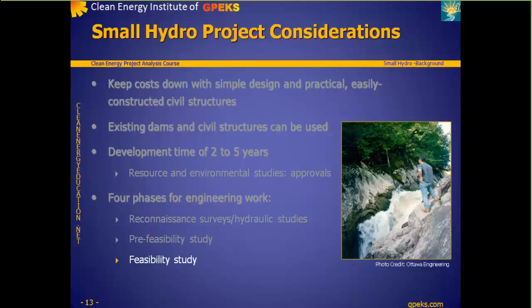Third, an in-depth feasibility study must report on foundations, probabilities of floods and earthquakes, design of major structures and selection of components, detailed cost estimates, utility interconnection, impacts on the grid, and financial feasibility. Fourth, in the system planning and project engineering phase, the electrical transmission system must be designed, tender drawings and specifications produced, bids and detailed design analyzed, and detailed construction drawings made.